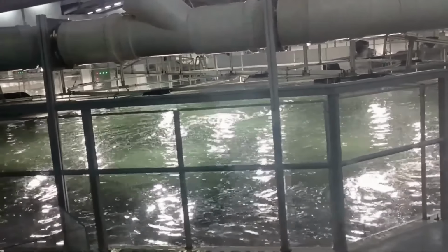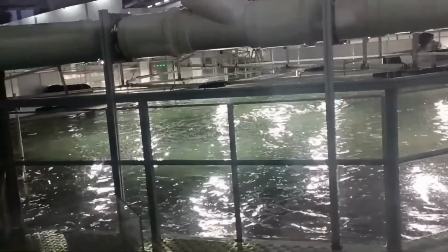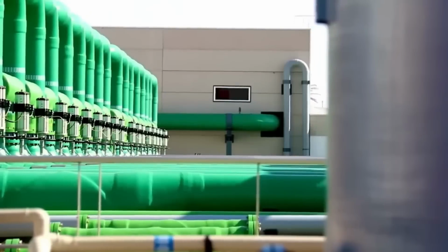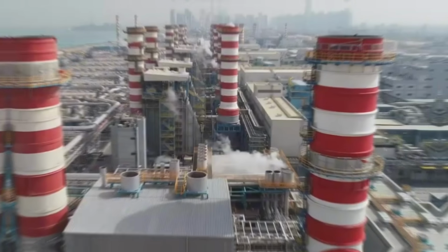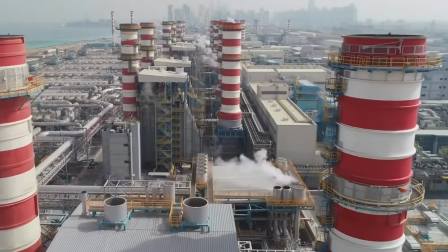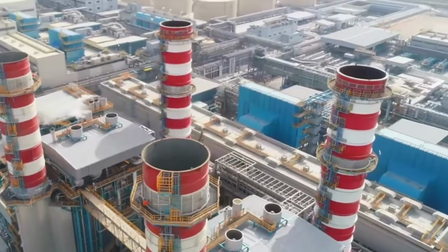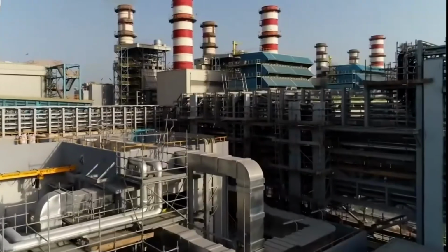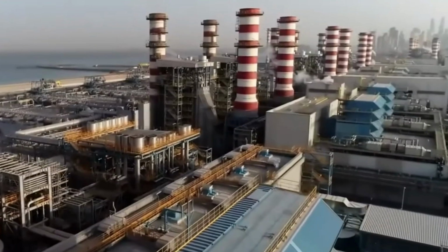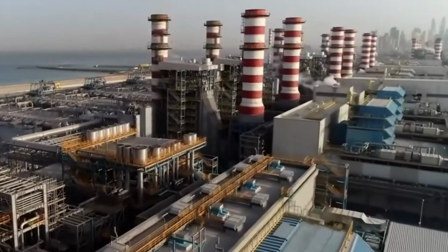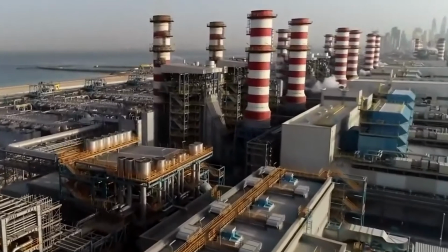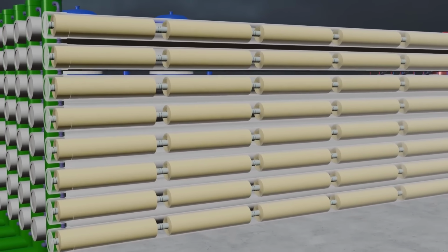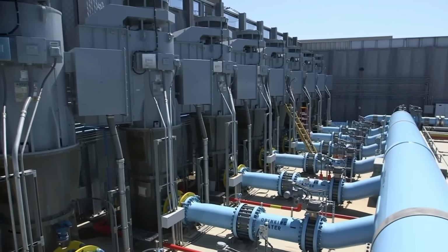Modern plants therefore send the pressurized brine through an energy recovery device. The main pump then only has to provide the remaining pressure required by the process. At Dubai's Jebel Ali plant, the energy recovery devices are rated at about 96% efficiency, transferring pressure from the RO reject stream back into the incoming feedwater. This does not mean the plant recovers 96% of all the electricity it consumes. But without this recovery step, modern seawater reverse osmosis would consume substantially more electricity.